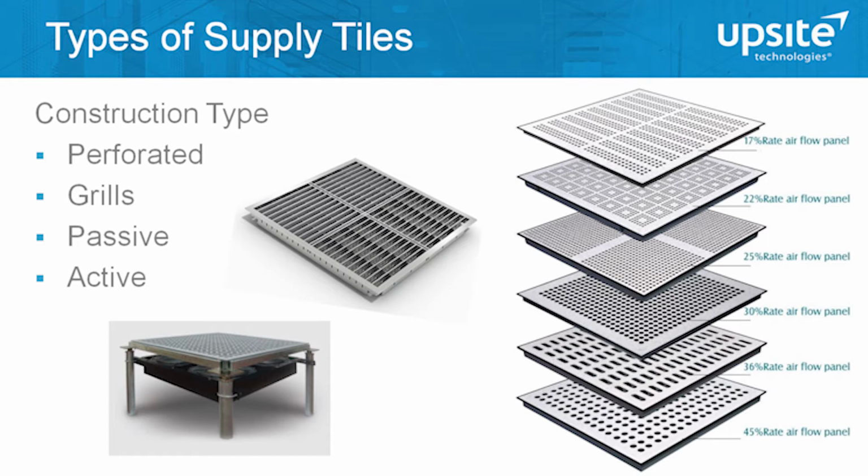Depends on how you look at it, where your perspective is. You can purchase tiles with fans attached, or you can buy a fan tray to attach to the supply tiles that you have. Obviously, it's a way to get more air out of the floor. I'd say in general that somewhere around 80% of supply tiles were inappropriately purchased, meaning that there was another way to get more air out of the floor.